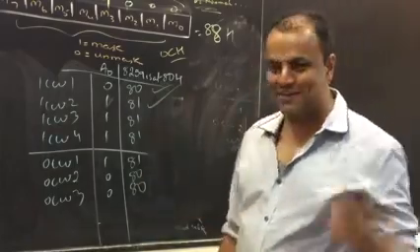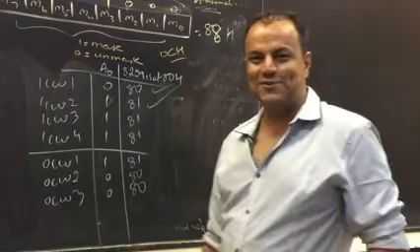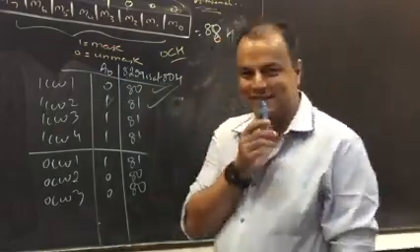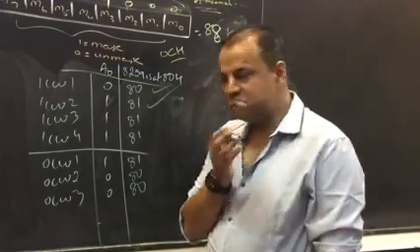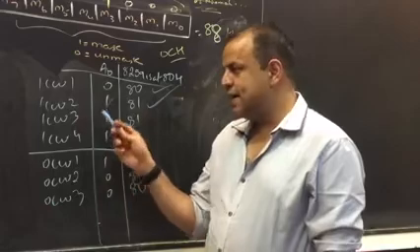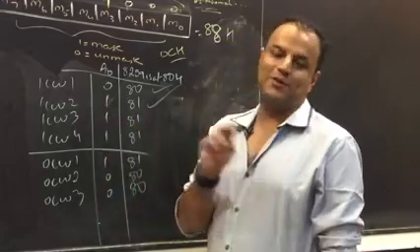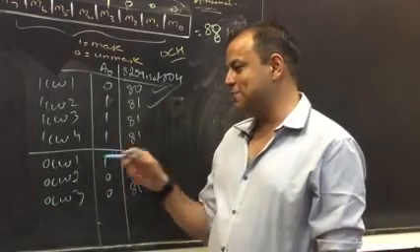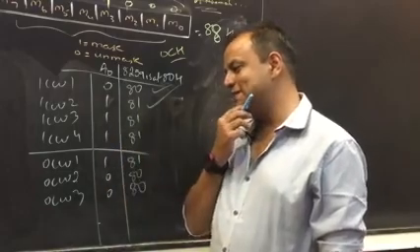Are you clear? Now you're left with 5 commands and still 2 addresses, 80 and 81, to know which command is coming at which address. I give you a command at 81. Could be ICW3, could be ICW4, could be OCW1. Cannot be ICW2. ICW2 is out of the picture. It cannot come again. That is for sure. But it could be ICW3 or ICW4 or OCW1. How will you know which one it is?